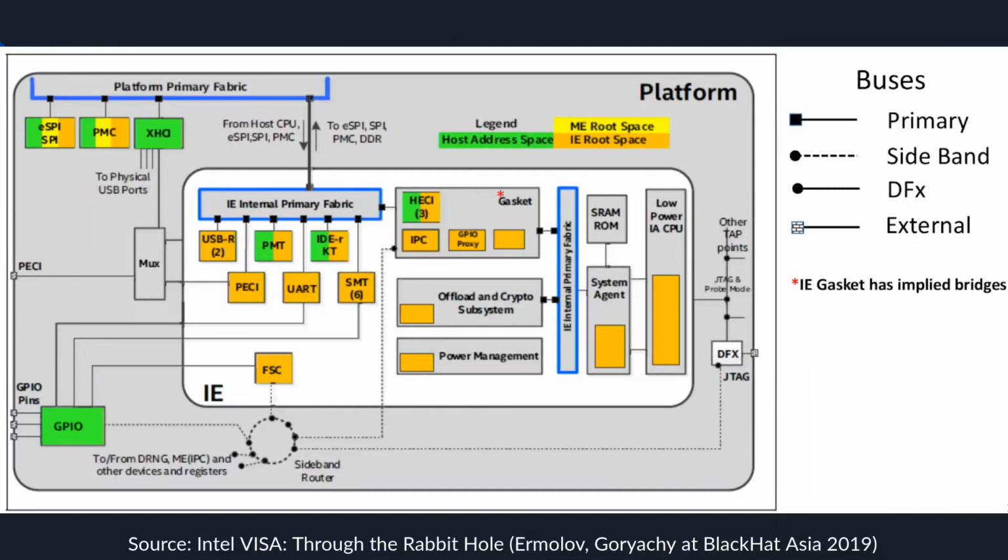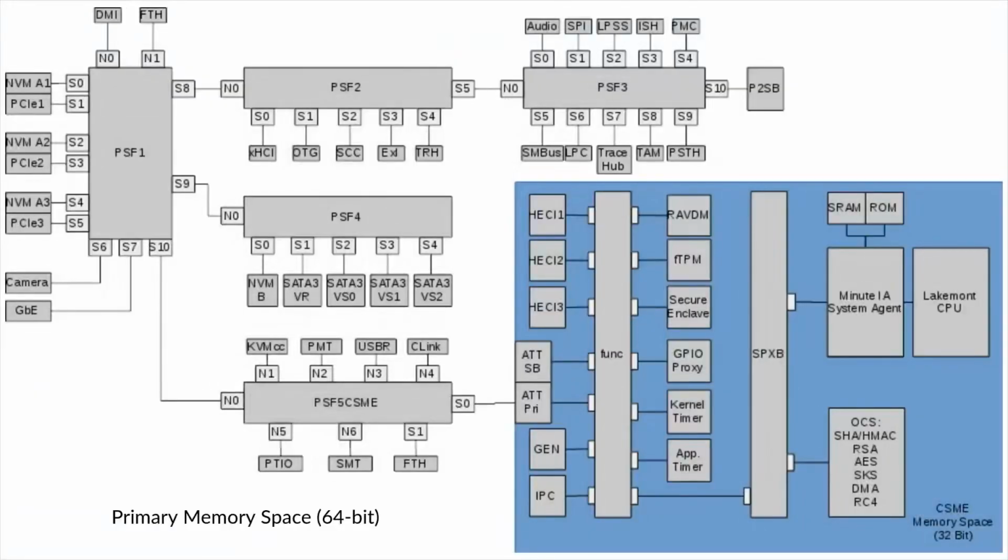So based on some of those files from System Studio, I tried to get a better understanding of this, which is this. This is the entire chipset. The little DMI block in the top left corner is what connects to your CPU. And all of the big blocks with a lot of ports are bus bridges or switches for the PCI Express fabric. Yeah, so there's a lot going on. The highlighted area is the management engine memory space, and the rest of it is the global chipset.